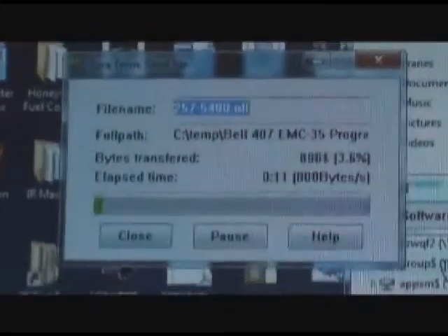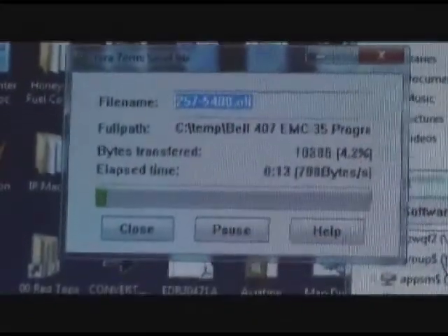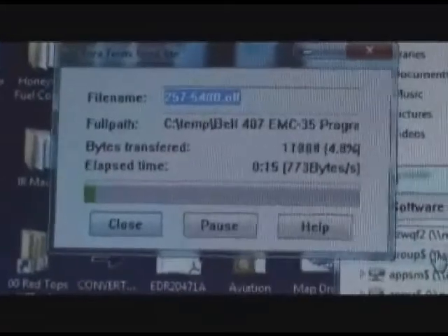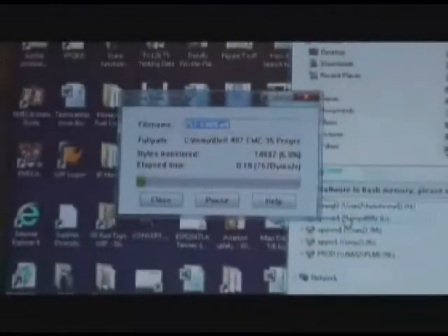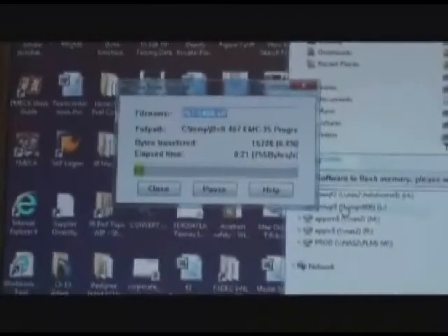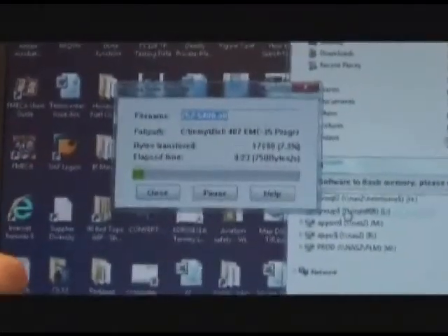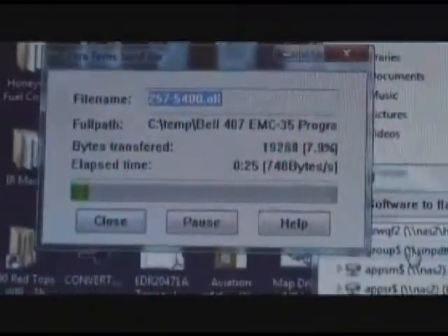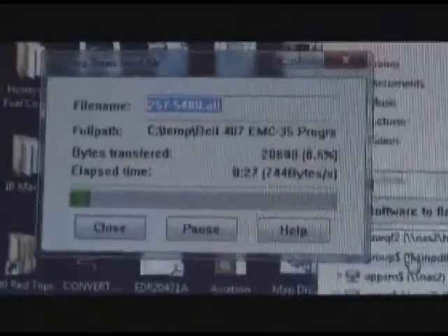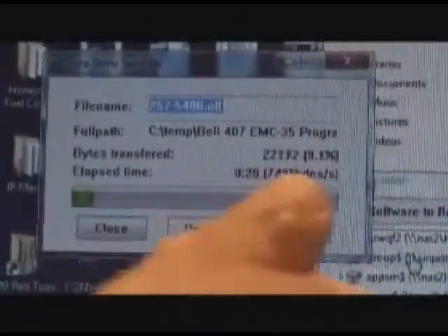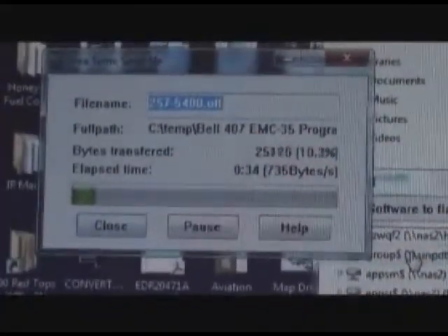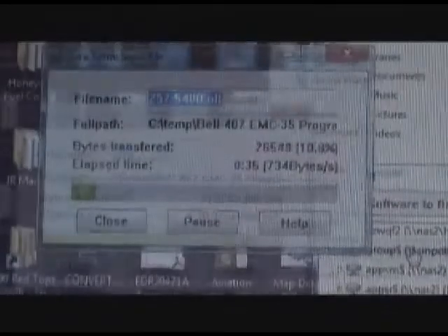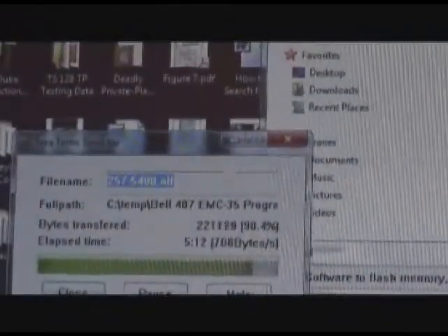So after that screen that says please wait a minute or two, it'll automatically jump to the next screen, and this is the screen showing that the new software is being loaded into the ECU, and it will progress along, so it should take 6-7 minutes, and you can see the progress both numerically and as the green bar shows.